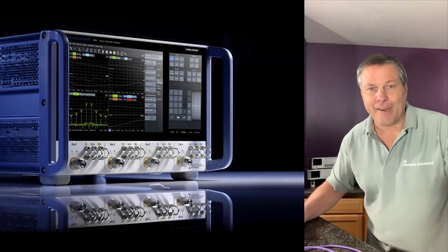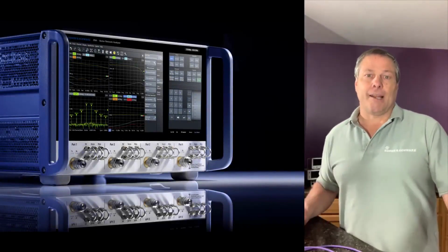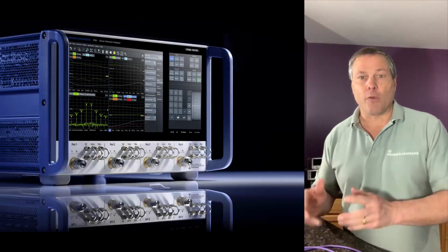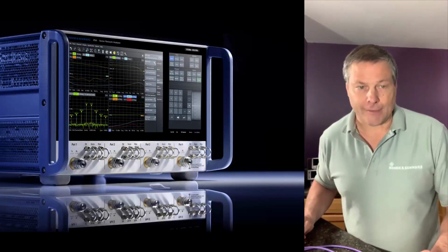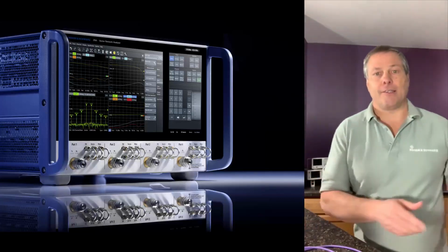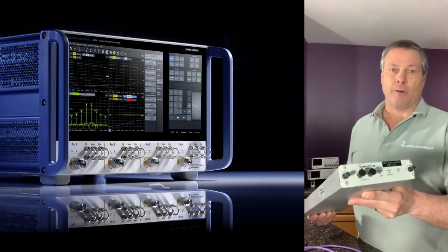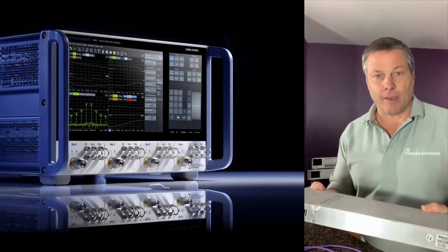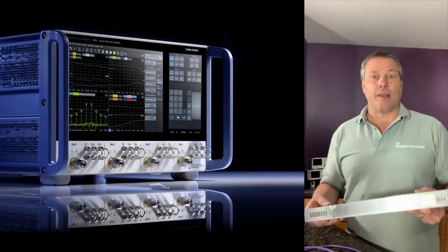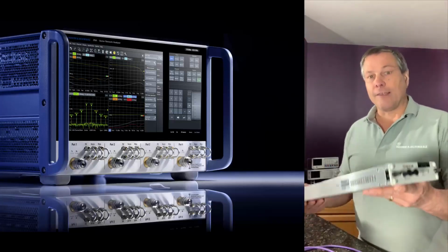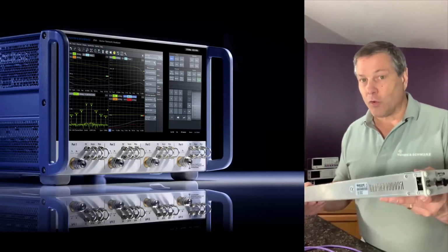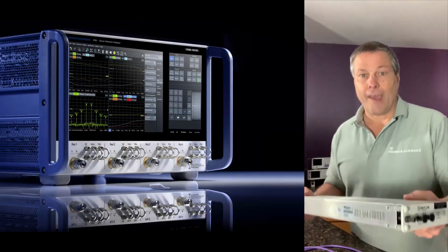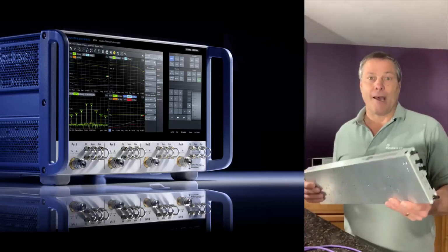Hi everyone, my name is Mike and I have 10 techniques that I'm sharing for making group delay measurements on frequency converting devices that have embedded local oscillators. For example, devices like this Mytek satellite block down converter, which takes a 20 gigahertz input signal, mixes it with an 18.75 gigahertz LO, and puts out an IF signal at about 1 gigahertz. So for a device like this with an embedded LO, I want to measure the group delay, and I have 10 techniques that can be used to make the measurements as fast, as easy, and as accurate as possible.